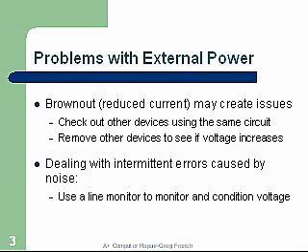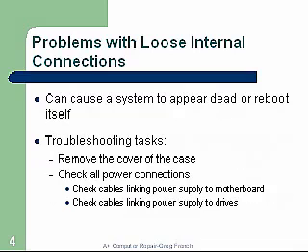Dealing with intermittent errors caused by noise: use a line monitor to monitor the condition of your voltage coming in. Problems with loose internal connections can cause the system to appear dead or reboot itself.